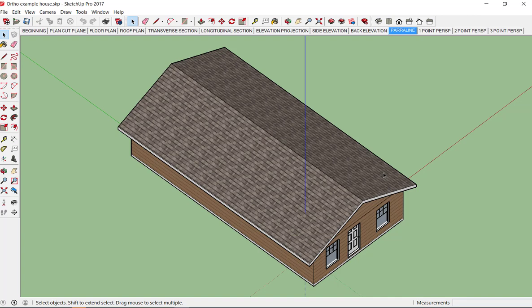There's two different kinds. There's isometric, where this angle here is 30 degrees and 30 degrees, and then there's axonometric, where typically it's 45 to 45 or 30 to 60. So these are more to have a 3D drawing that still is to scale, but as you can see, you wouldn't show this to a client because it's not realistic. Your eye knows that this is not the way your eye perceives things.